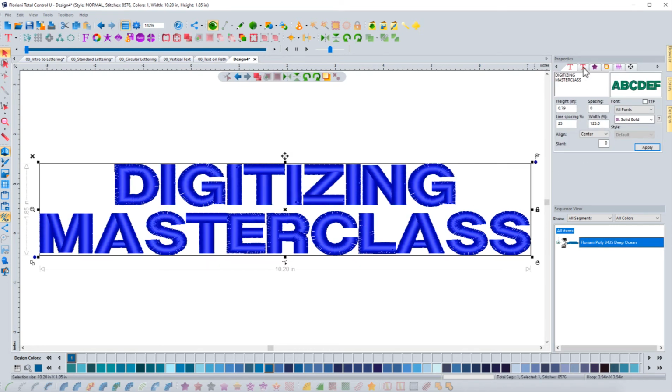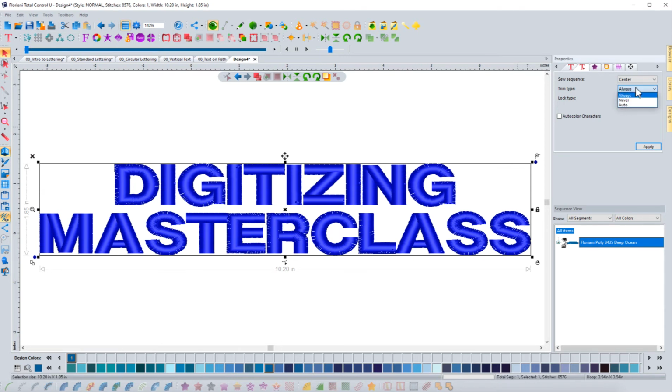If I come back to this text plus with the lettering selected, you have trim type, and right now it's set at always. If I click the box here, you'll notice that I have the option to always trim, never, or auto. And what this trim type means is between each letter. So if I wanted to always trim between letters, I would choose always.